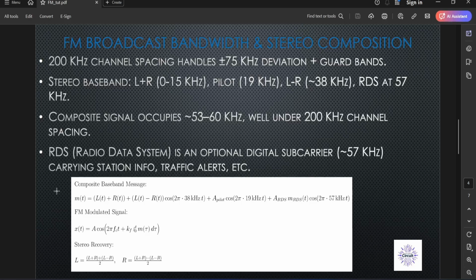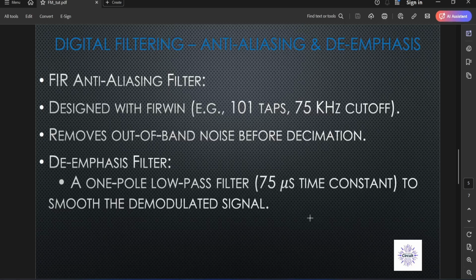But before doing the decimation, because if there are tones higher than the final decimated frequency, they will fold back into the main spectrum and may cause SNR degradation, I filter to remove all the unnecessary noise in the band, then I decimate the signal. I do this just using an FIR filter, right?